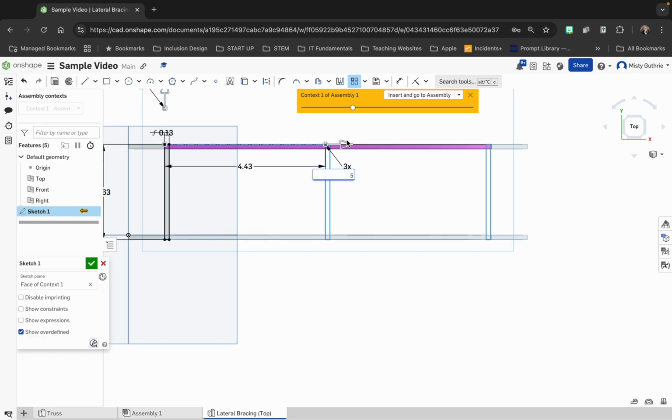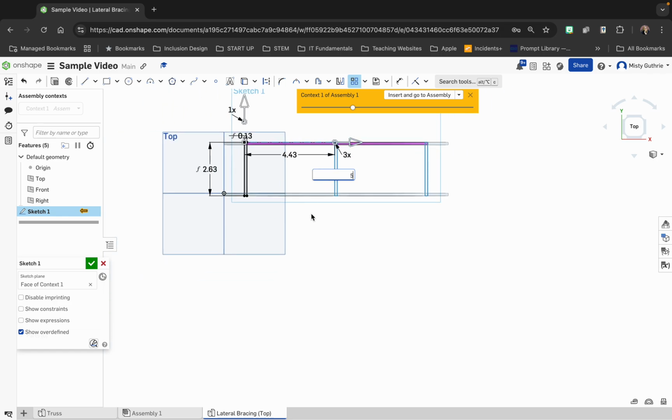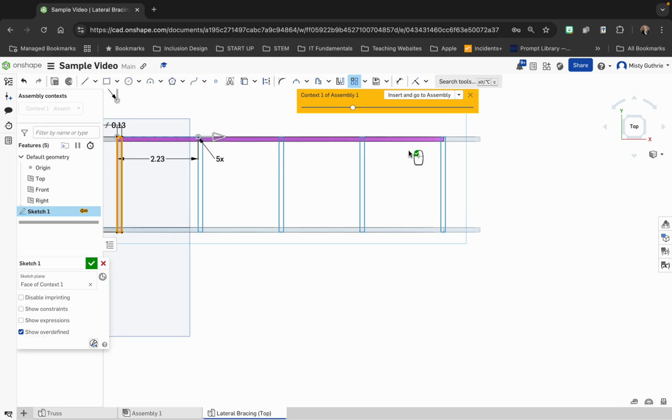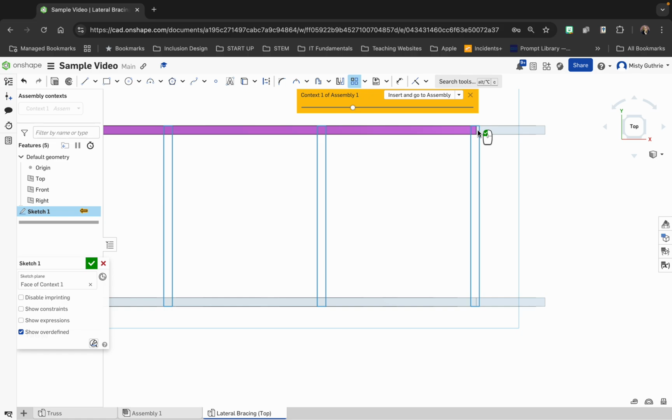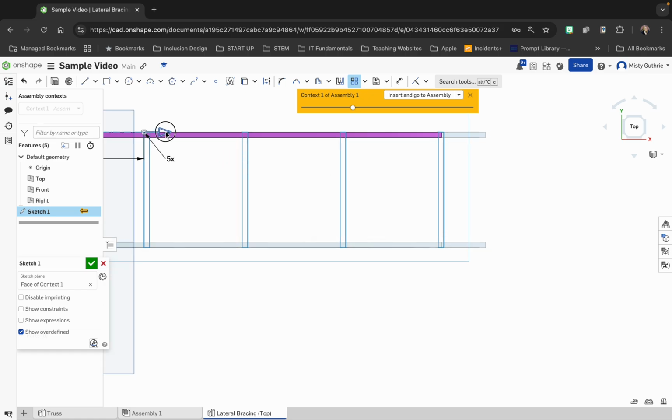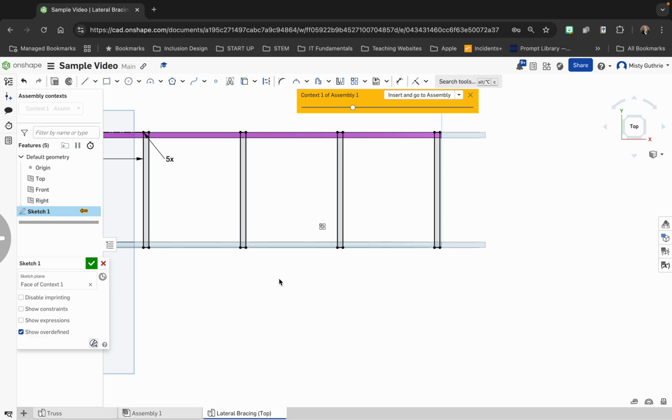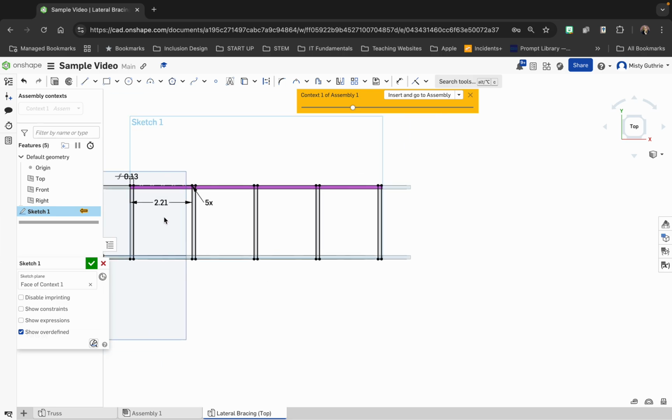And I'm going to zoom out. Oops. Obviously I went too far. I think I set it and changed it to 5 at the same time. All right. Notice that that's hanging off the top. I don't want that. I'd rather it be slightly shorter than be hanging off. So that will do. And it automatically placed them in equal distance apart from each other because it's a linear pattern. If I'm content and happy, I can green check.